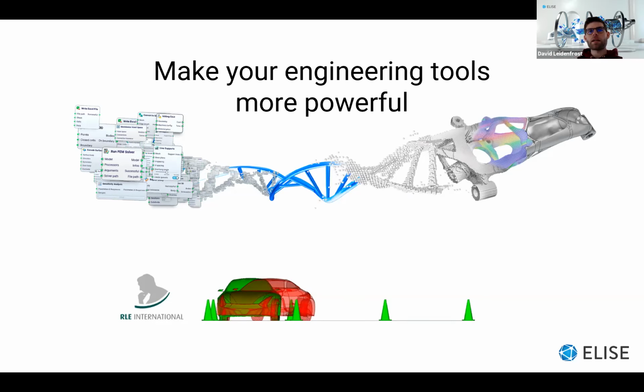Since we define everything parametrically, we can just have sliders, and let's say we want to do a thickness optimization of a casting part with different ribs. We can simply change the thicknesses or heights of the ribs by parameters, and then you can even connect these sliders to a parameter study or optimization, and overnight automatically generate different variations of the part, which are all evaluated regarding the boundary conditions, the constraints.